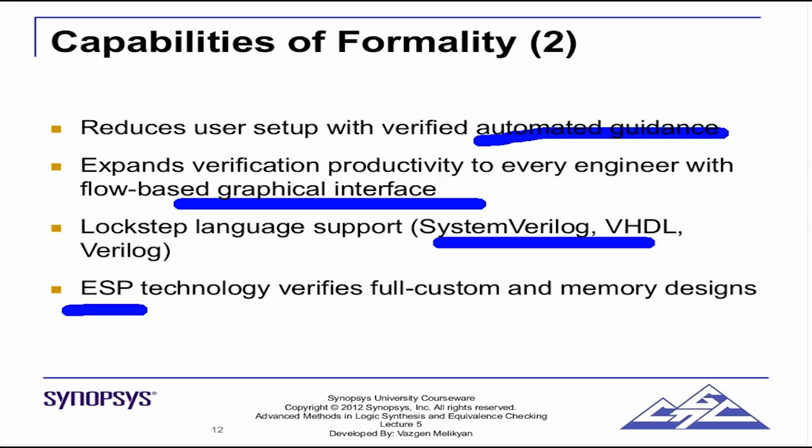It's a very, very unique tool, and it addresses a very niche segment, like memories, full custom memories, where memories are built separately, they are not synthesized. But the code is written for simulation, which is called a behavioral code, and you want to make sure that the behavioral code in fact matches the netlist of the memory. The netlist of the memory in this case is a transistor level netlist, and this tool is able to verify whether the behavioral model, which is written separately, is functionally equivalent to the transistor level memory netlist.